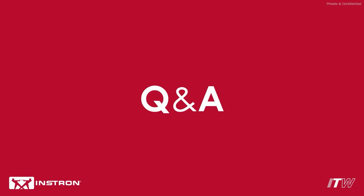Wonderful. Another one for you, I think, Dr. P. What is setup low power mode typically used for? Okay, so that's great. That's maybe not software related, but system related in terms of how our system works. So setup we have off, obviously. We have low setup and low power, then high power or run mode. So setup mode gives us some more safety in terms of restricted machine movement rate.